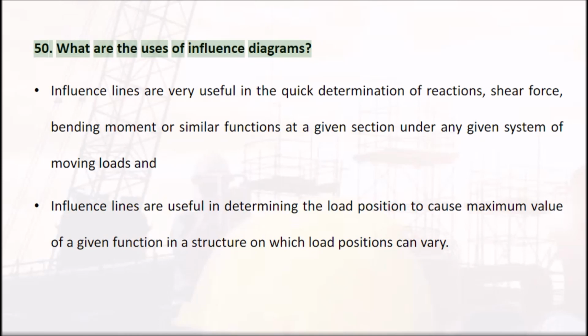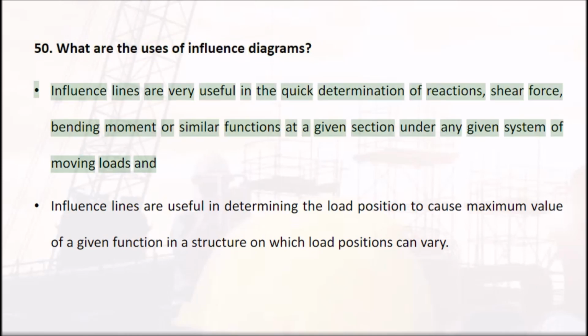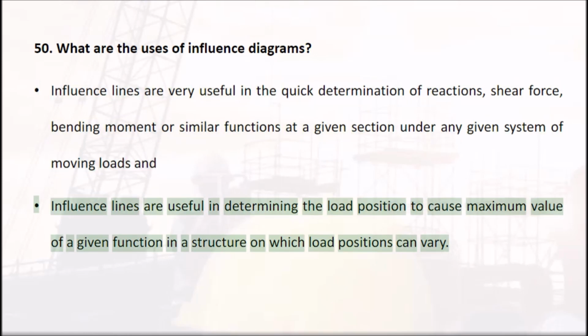What are the uses of influence diagrams? Influence lines are very useful in the quick determination of reactions, shear force, bending moment, or similar functions at a given section under any given system of moving loads. Influence lines are useful in determining the load position to cause maximum value of a given function in a structure on which load positions can vary.